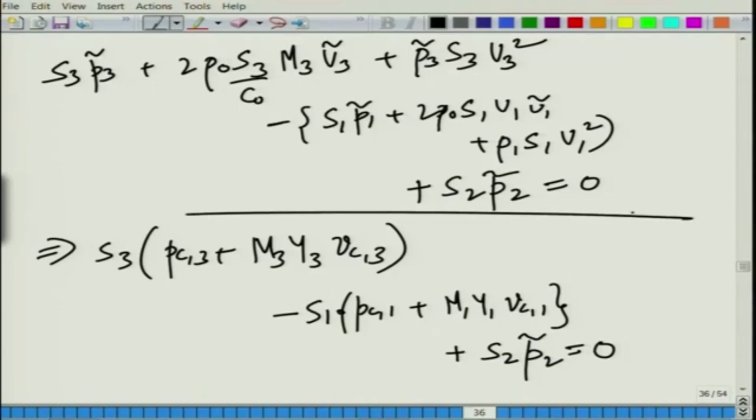Now, P2 by V2 is equal to Z2. So, what do we do now? Z2, that is the impedance seen right at the entrance of the annular cavity, and that we know is nothing but minus jy2 into cot of k naught L2. In the annular cavity there is no mean flow. So, that is why we are getting k naught. So, after doing all these things and substituting, making use of this relation, what we get after significant algebra is